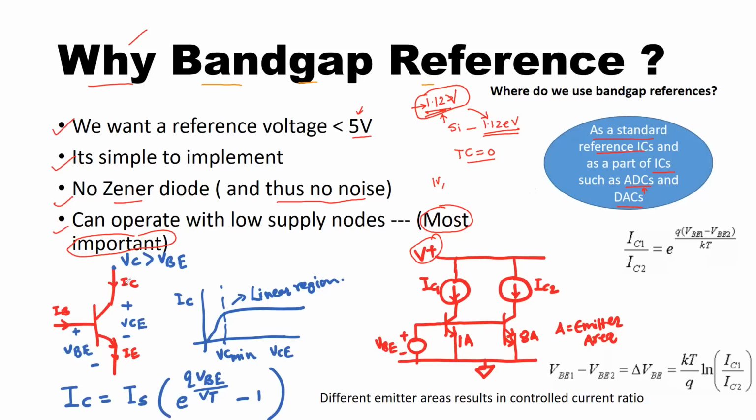So what we know is we need the BJT as shown right here. As you can see, this is an NPN transistor with the currents and their directions indicated. The voltages VB and VC are also indicated, and we want to generate the reference voltage first, which will have the temperature behavior associated with VBE.